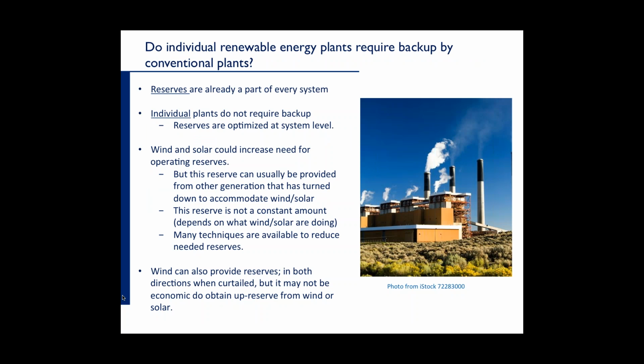People often ask, gee, I have a 100 megawatt wind plant. Don't I need to have a backup for that wind plant? And the answer is you could, but it would be needlessly expensive because we don't back up individual units in the power system. Reserve policies and methods that we have for calculating reserves take into account the entire system. And we never back up individual plants unless there's some sort of a market imperfection that might otherwise require me to do that. But in every case, if you're building an individual backup, you're needlessly increasing cost.